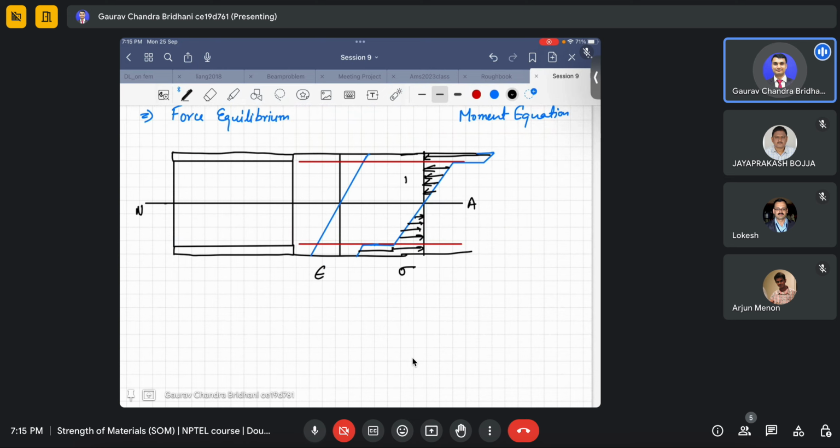Okay, so I will call everything above the neutral axis 1, and everything below the neutral axis 2. So I say the total force due to the portion above the neutral axis is the integral over A1, and the total area I am calling A1. A1 comprises both the plastic core and the aluminum above the neutral axis, and the plastic core and aluminum below the neutral axis is A2.